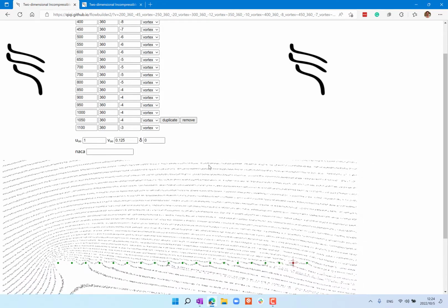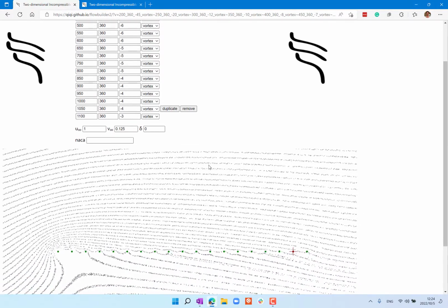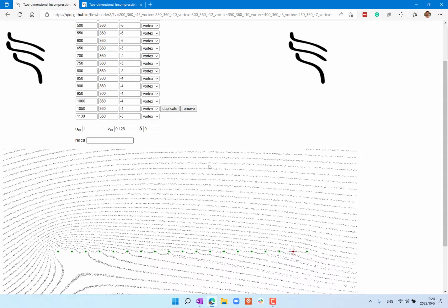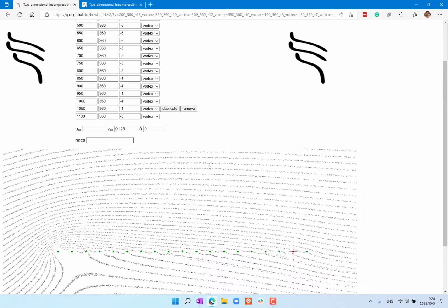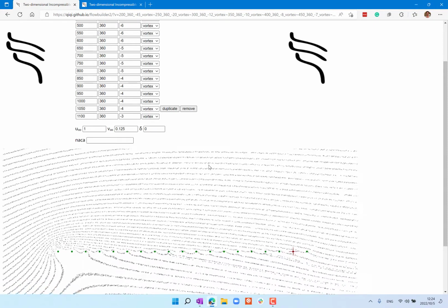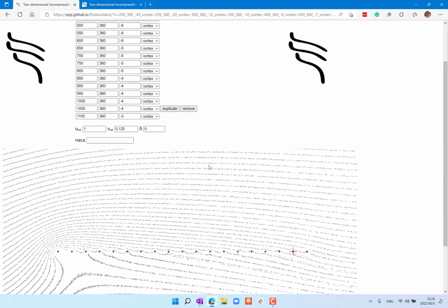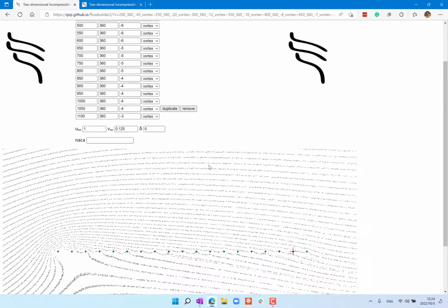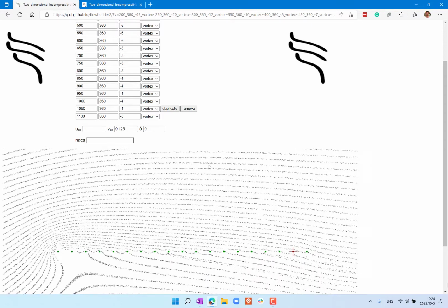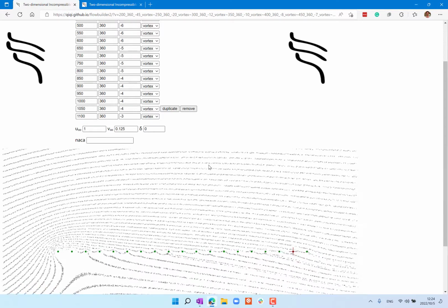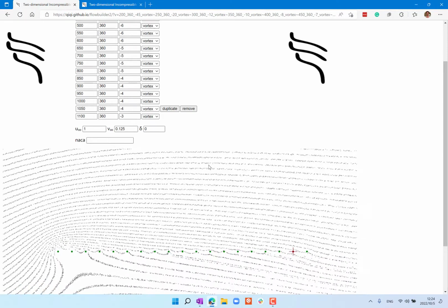So if you do aerodynamics, a very important location is actually the center of lift derived from this function. You can work it out analytically. This is exactly at the quarter chord, a quarter from the leading edge, halfway between the leading edge and the middle of the chord. Okay, this is universal because the function is universal. For any airfoil, okay, for any symmetric airfoil,